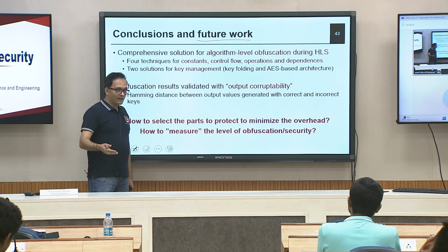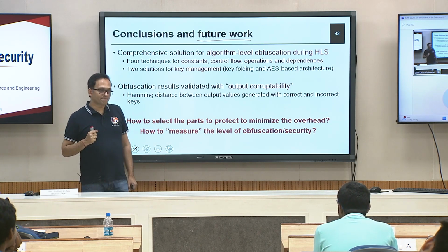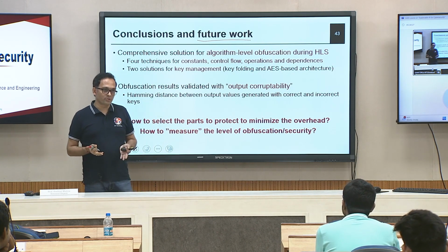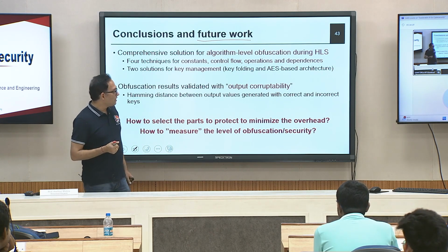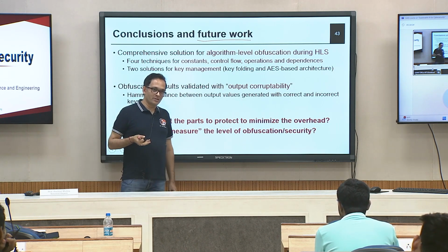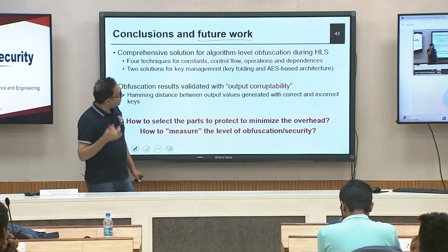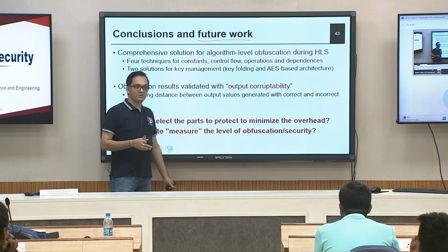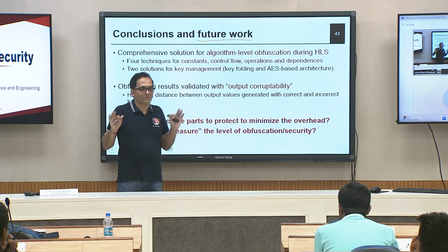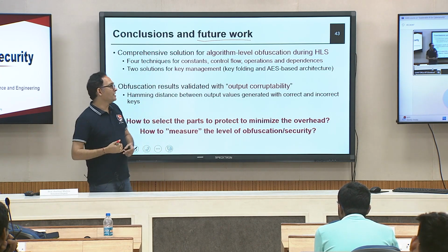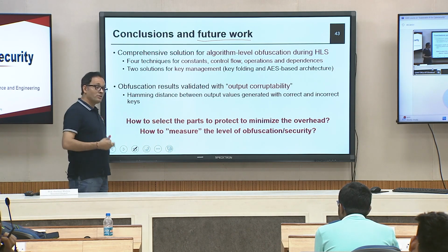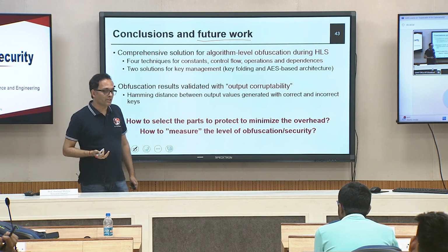So, in the second half of today, I will talk about some attack technique, and it is not brute force. Nobody will apply brute force with 400, 500 keys, right. I will show you that you can actually use the theorem prover or SAT solver, and you can make an attack, and we can break those kind of circuits which may have even 200, 300 gates. Okay. So, it is not something where you lock and you are very happy. Attackers will also try their intelligence, right. So, they are intelligent people. So, in a formal way you can actually scale your attack to some 400, 500 keys also.